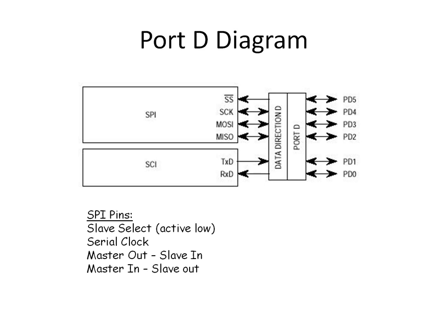Depending on whether the 68HC11 is configured as a master or a slave will determine the functionality of these last 2 pins. If the 68HC11 is to be in charge of the serial clock line, meaning it's controlling the timing of the data that's being sent out or received, then it needs to be configured as a master. If it's not in control of the serial clock line or the timing of the data, then it'll be configured as a slave.